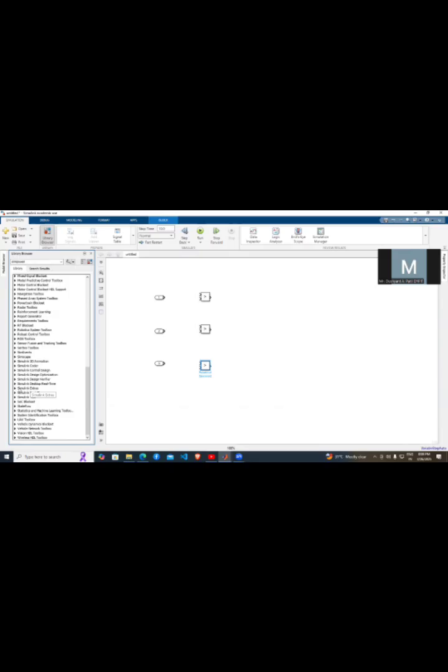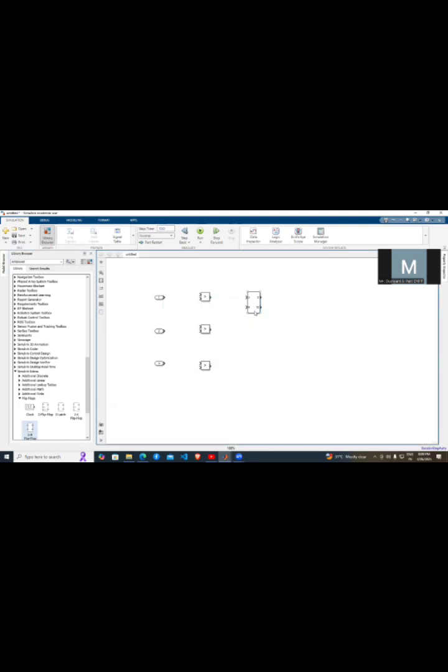So you have to come out from the Simulink library and go to Simulink Extras. In Simulink Extras, you have to find the flip-flops, additional lookup table. There is a block that is a flip-flop. In flip-flops, we need the SR flip-flop. So we will drag it onto your sheet. This is your SR flip-flop. We will press Control C and paste it two times, and arrange the position in front of each relational operator.